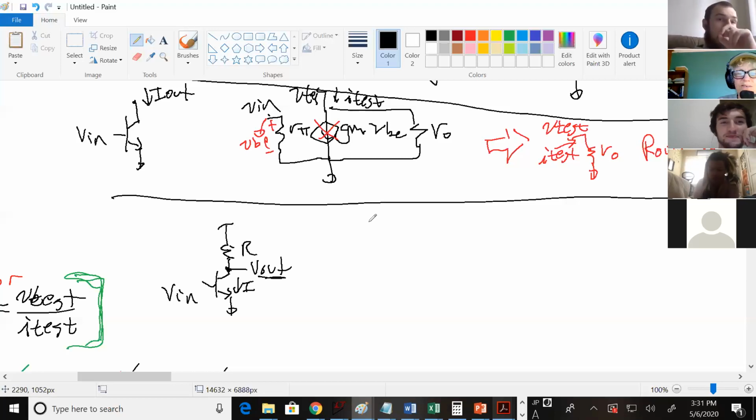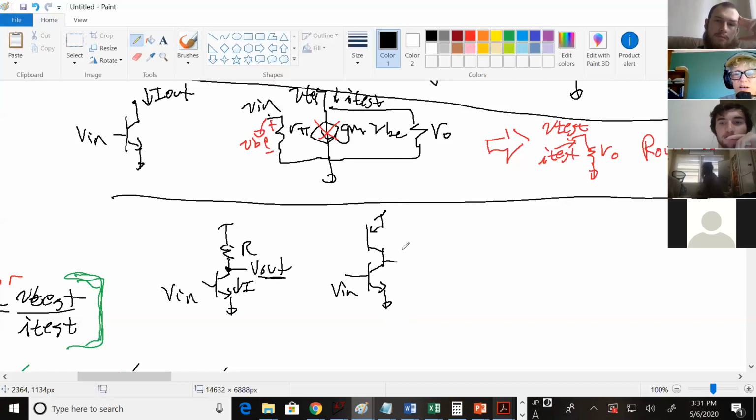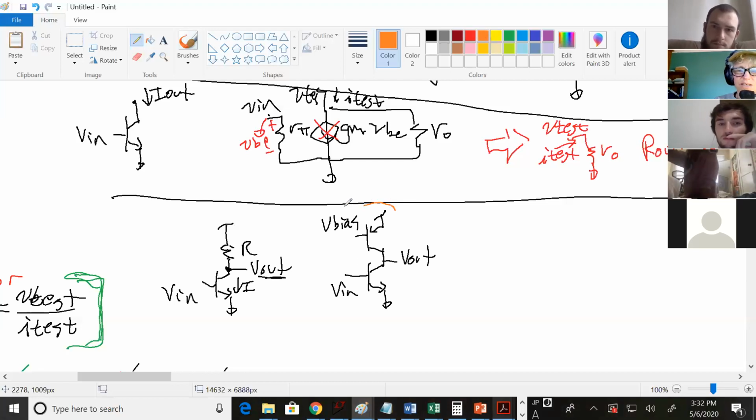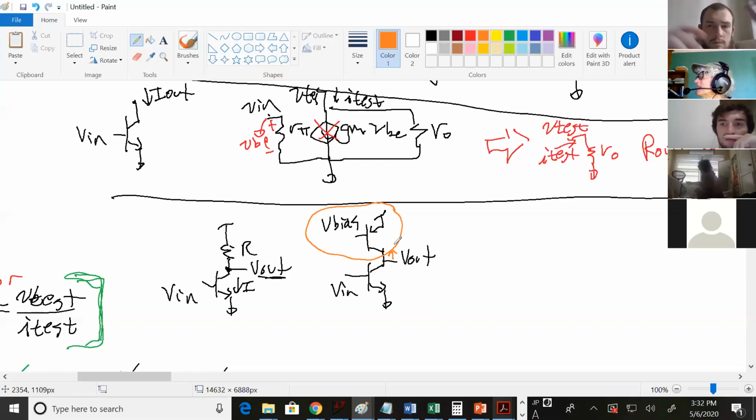So there's a limit to how big you can make that resistor. So we said, well, this is interesting. If I do this, wow, all of a sudden I get a bigger gain. So on this one, this right here is acting like a big resistor. That's how you get big gain. So my question to you now is, how big a resistor does that look like? And in this case, you're looking up this way and saying, how big a resistor does it look like looking up into that transistor? So how would you find that?